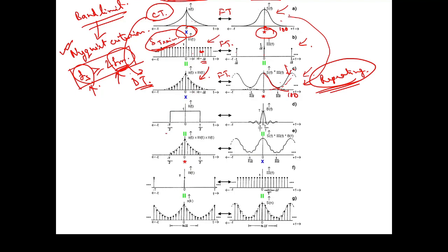So we will be using a filter window, which is basically a window, to get a section of the signal, and once we get that, we have this time limited signal. Its Fourier transform is like this. See, it was quite smooth over here. After time limiting, it has become somewhat wonky.